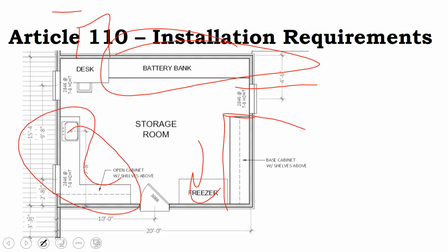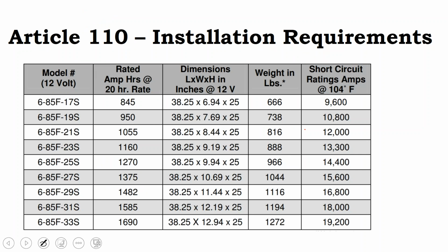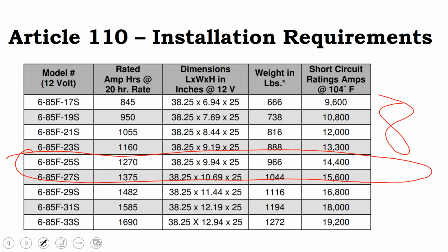Let's just take a look. It depends on your battery technology. Lead acid takes up a little bit more space than lithium ion. It depends if you're doing off-grid. It requires a much larger battery than on-grid. But here are off-grid lead acid batteries. And these are the ones we ended up with, and we had 8 of them. And they're over 3 feet long, 2 feet high, and 10 inches wide.